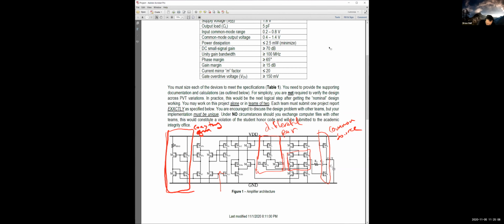All right. So all of this is a bunch of bias circuit that you guys are going to have to analyze and kind of sit down and think through. We'll talk about this very soon. And we'll talk about this part very soon as well. This is what's known as the compensation circuit. So this is to position the poles and the zeros where we want them and shift around the frequency response. Okay.